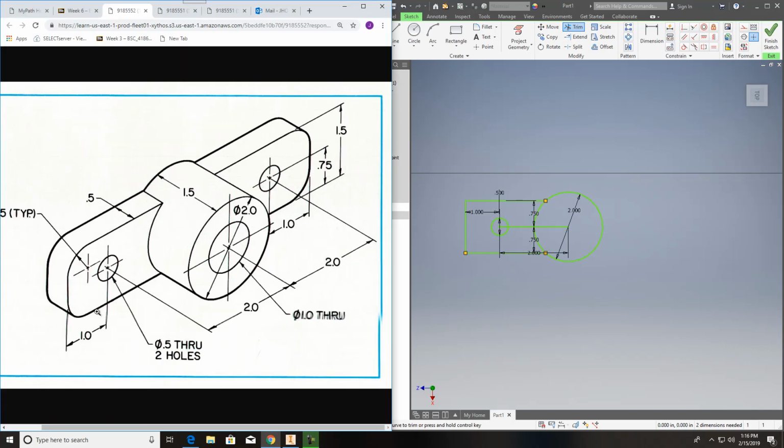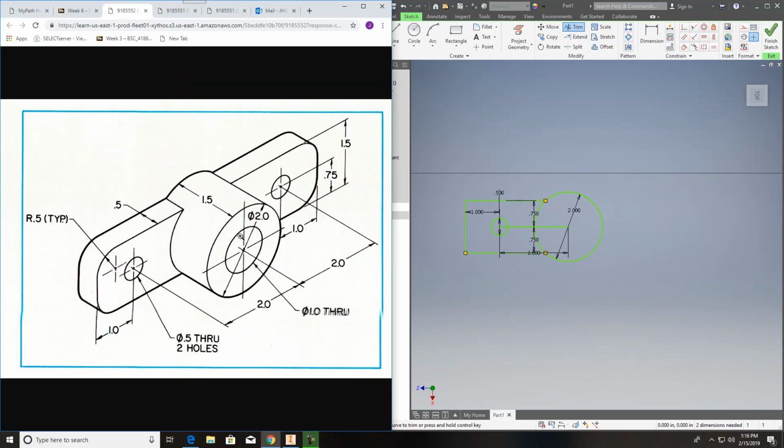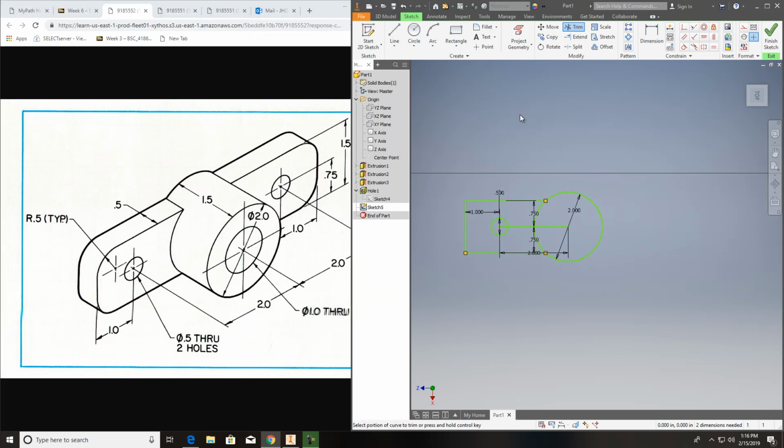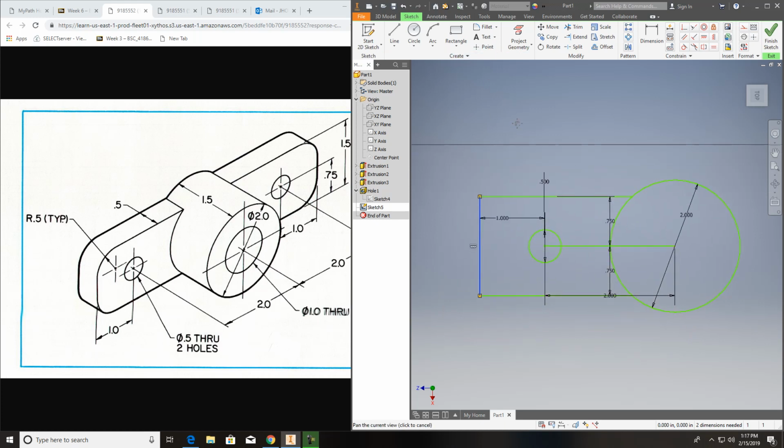And it's got a fillet on the end of it. Radius is 0.5, so we'll go ahead and stick that radius on here. We can do that in sketch mode or in feature mode, whichever one you want to do. Fillet, and I can put 0.5. It's a pretty good size fillet. Fillet, 0.5. There we go. And then here we go again.